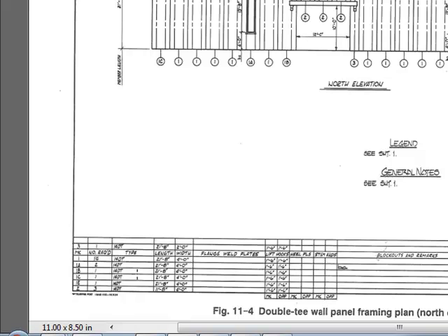And then the next page talks about the steps on page 153 for the beam framing plan. It's basically kind of the same. Determine the sizes that you need based on your calculations of the center column dimensions. Now, this is important. You'll have to read this. You'll determine the length of your beams, because there has to be a 1-inch joint between the beams. So that allows for movement so they don't rub against each other and break each other. So once you know your center line, then you can go off of that half inch either way, and that'll be your beam length.